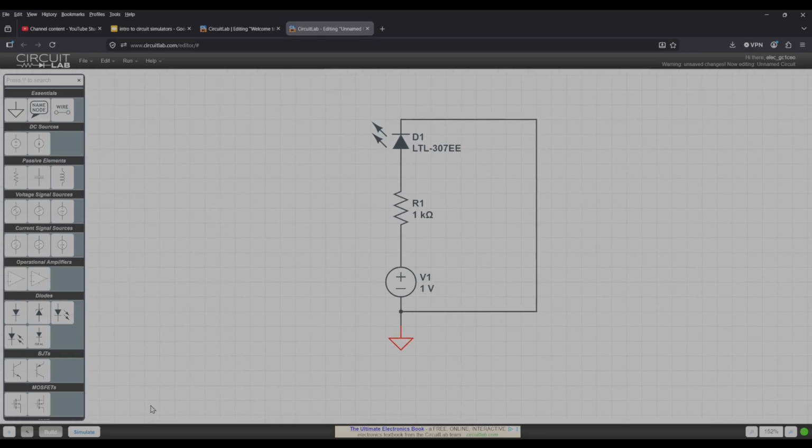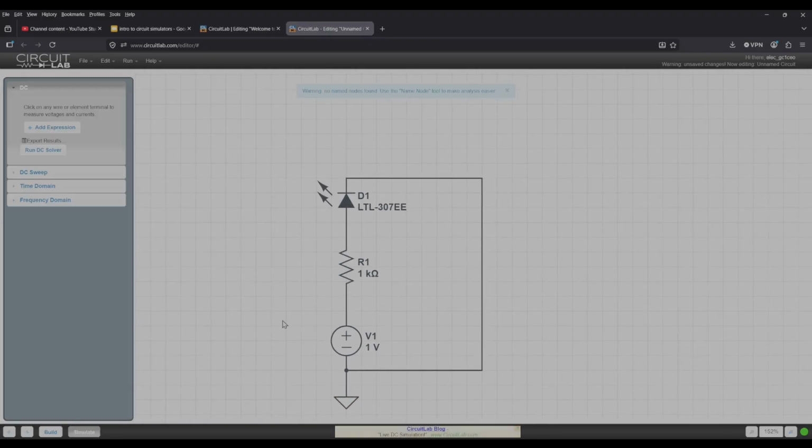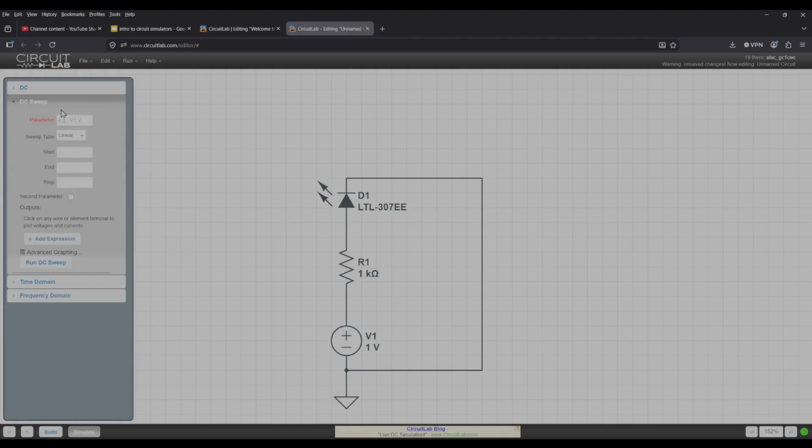All right, now simulate, but what kind of simulation do we actually want in terms of numbers? Again, this is a lot simpler in LTspice, but it gives you an idea. So we could do DC sweep. Could pick this. Let's just say what happens at 0 volts. We'll end it at 10, and we'll do a step of 1. Okay. Select one output.